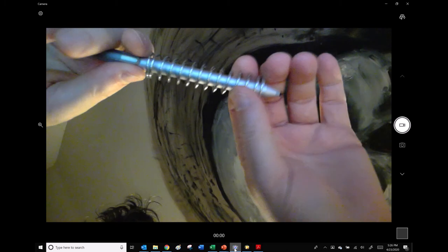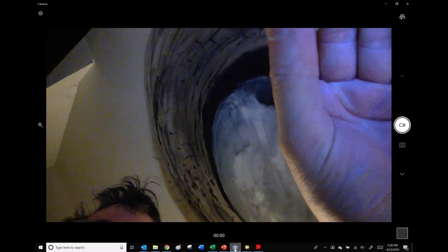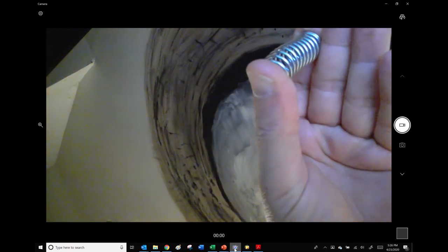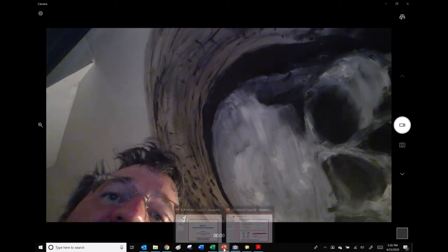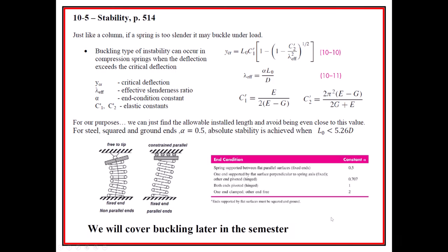But you might have to worry about, I don't think in this case, but the diameter can change a little subtly when you're squishing it. I think it actually gets bigger. I don't know. Anyway, it is something to consider. Buckling can be an issue, and the end conditions of the buckling, whether there's a pin right there, or whether they're flat plates that are constrained to be flat. The truth is, though, that this isn't a topic I like to deal with in springs because it's difficult to relate it back to the fundamentals.